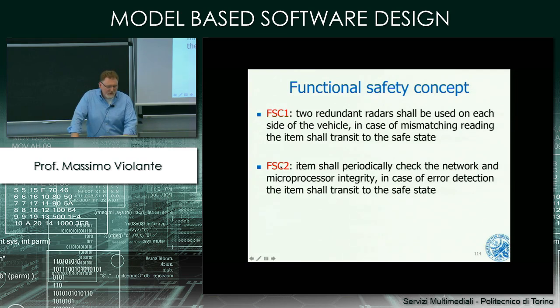Another functional safety concept: the item shall periodically check the network and the microprocessor integrity. If a failure is detected there, the item shall enter the safe state. Okay? Is this clear?